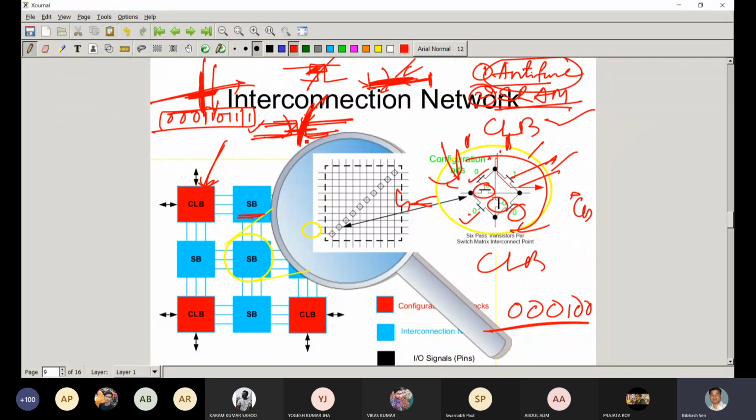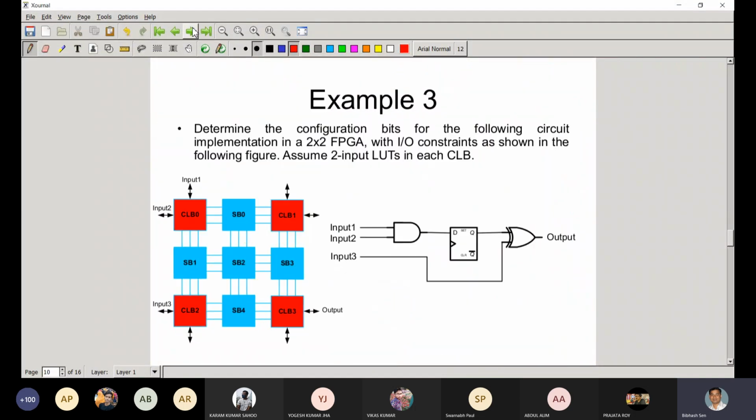In anti-fuse, when a voltage is applied, the connection is built up. That happens in the case of the SB. That's why it is called anti-fuse technology. They are mostly joined to each other by applying voltage at the joint, and as per your requirement they build up. But mostly we use SRAM technology in the FPGA. So those are the SB's connections we discussed.